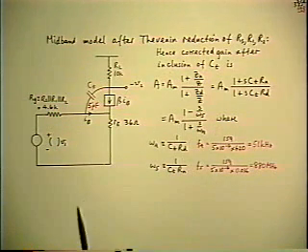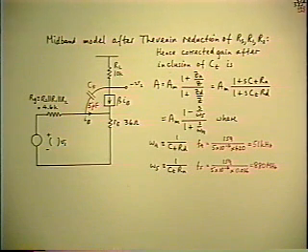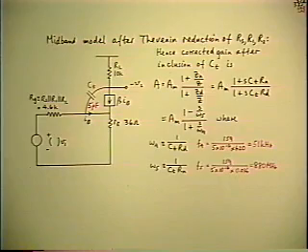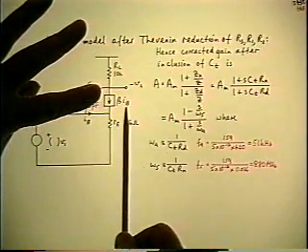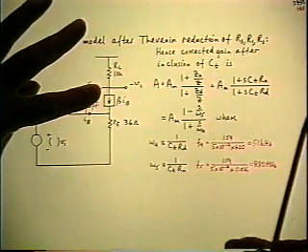And you see, it's the same structure that I gave as the example earlier on, which could lead to a right half plane 0. It's the parallel combination of two signal paths which change places, going from 0 to infinite frequency. This is exactly that situation. Because without the capacitor, the reference circuit is a high gain inverting amplifier.